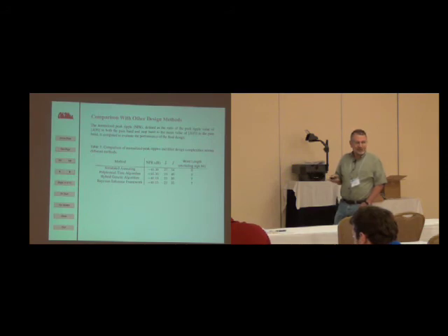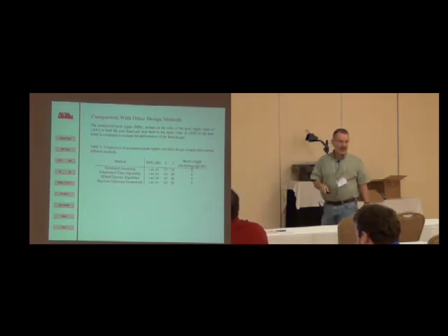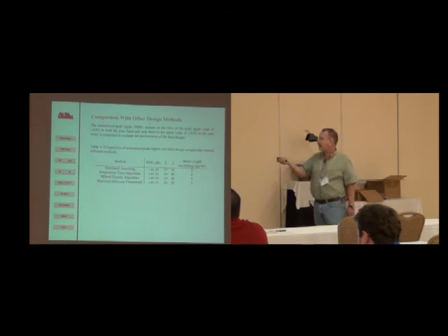But the other thing to be said about this hybrid genetic method is that if you want to do a band-pass filter or something other than this particular low-pass filter, it would require very significant fiddling with and changing. It's something that requires a lot of intervention by the user to make it work. Whereas with this, once you set it up, you turn the crank, you want a different filter design, you just put in the requirements and it pops out. As I'm trying to say, it's robust.